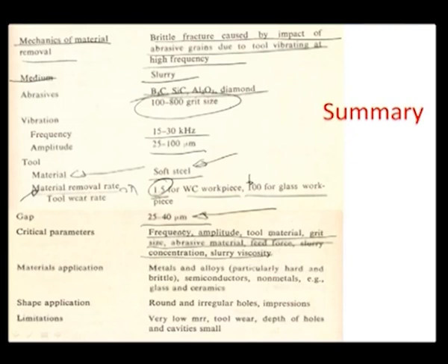And there are tremendous applications of these processes, particularly in the semiconductor industry, and because MEMS or microsystems is a fallout of the semiconductor industry, we do have a lot of implications of using mechanical energy application processes like AJM or USM in the MEMS industry, or microsystems industry as such. So, some of the limitations of this process are low MRR, as I already illustrated.